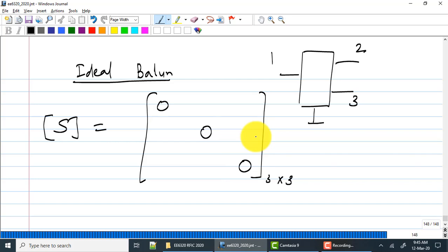You expect something like this. So you put in a power P, half of it goes one side, half of it goes the other side. Make sense? Now, just confirm for yourself that the simulator is splitting power and not voltage. Normally that's the way it should be set up. It should be splitting power, as the parameters are in terms of power. So these should be the ideal ones.